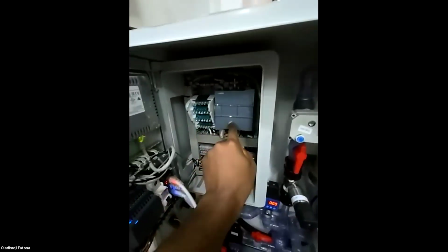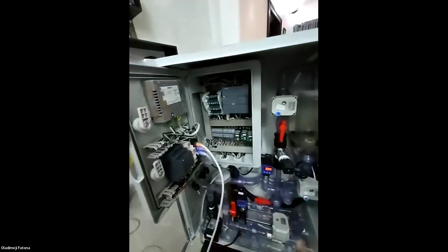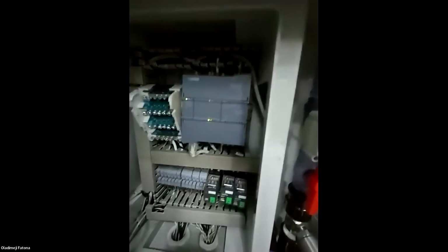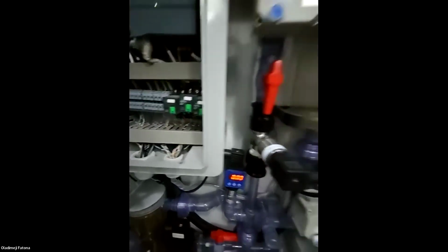Then here you have a power supply. Here the PLC is linked to an Ethernet switch. The HMI and PLC are linked. This is just a small test thing that we use. We use the small S7-1200 because we already know the number of IOs that are required, so we just size it. We have a 1200 PLC with the DIs, DOs, and then we use the limited expansion slot for the analog output. Here you can see the relays which will function as output.